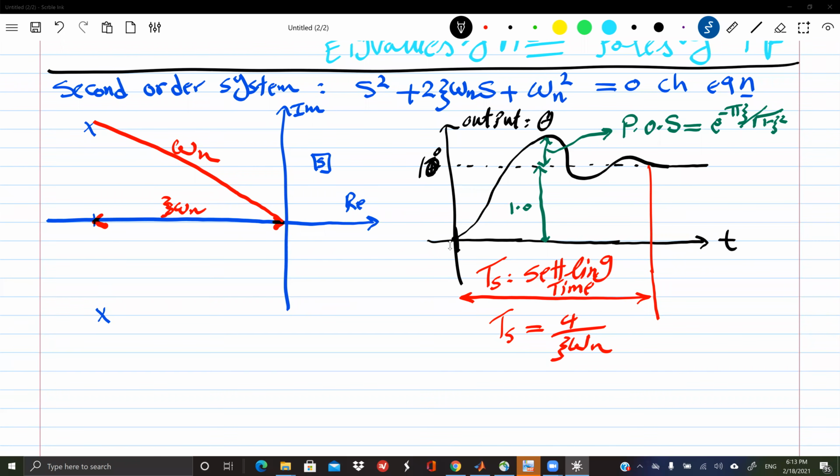Okay, so consider this hypothetical situation. The pilot's giving a command to 10 degrees, steady state 10 degrees angle of attack. Fine. So I'm doing landing with a relatively large angle of attack, which is typically the case. And the airplane is well designed, so the settling time is fast, like a couple of seconds. Very good. Awesome. So I reach from here to exactly the value that you like in a couple of seconds.